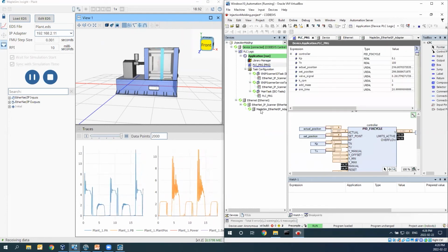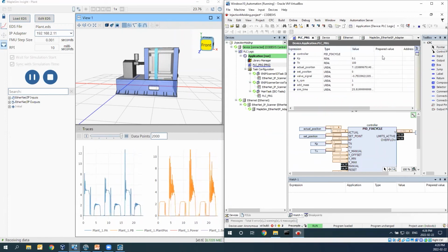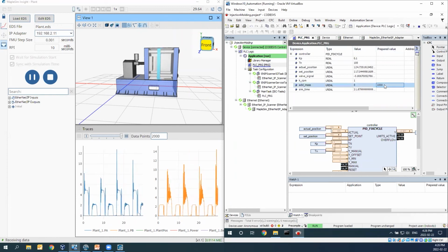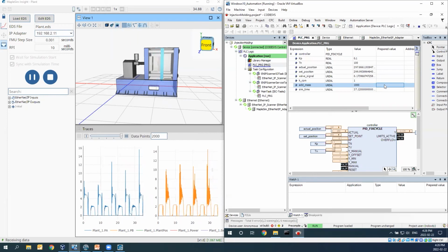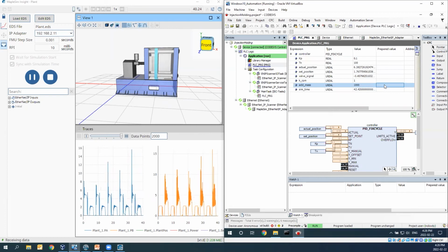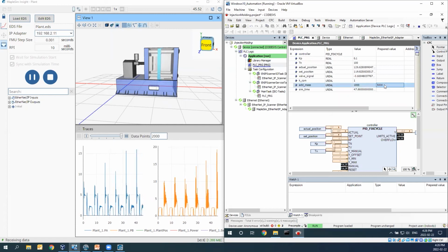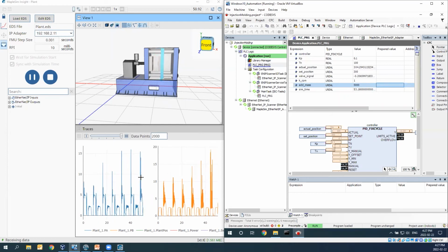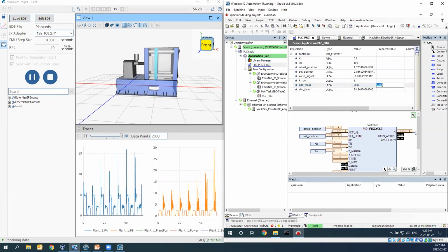So I can go to my PLC program and look at these variables. I'll move some things here and I can pass different values. So for the added mass, I can increase it to 1,000, right? Pass this along. And I'll try not to go too crazy with my steps. If I all of a sudden give it too much mass, it might cause some errors in the integration and cause my model to run into problems. But we'll try to increase this a little bit more, maybe 5,000, right? We'll be able to look at the results, but you can already see that some of the pressures are increasing as I increase the mass here. I'll bring this back down to 0.